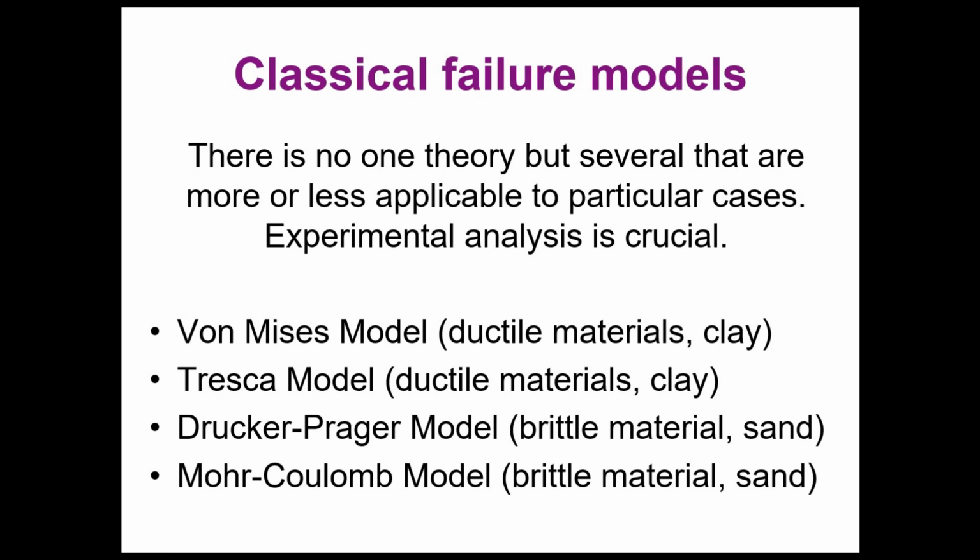They behave in a linear elastic way, at least for a range of loads, but in soils it doesn't happen like this. Soils are usually anisotropic, so they have different mechanical properties in different directions. They are made of particles, so they are not even homogeneous as metals are.